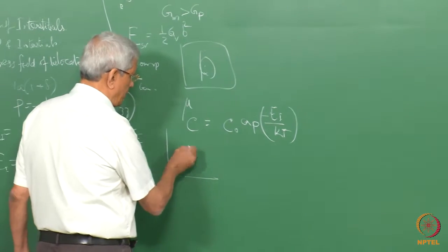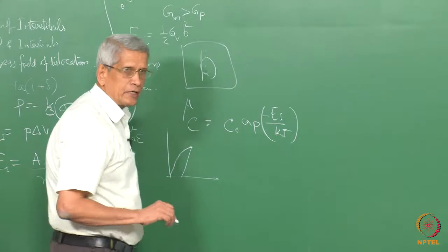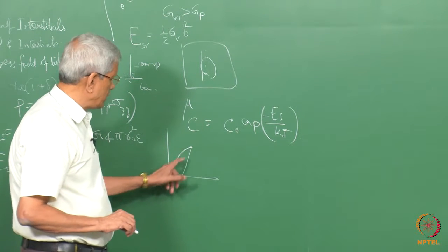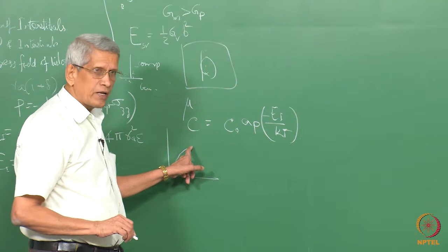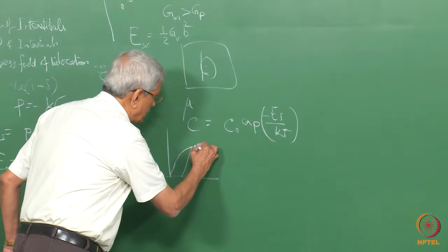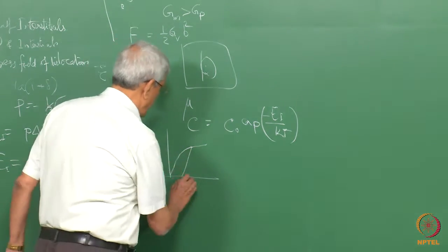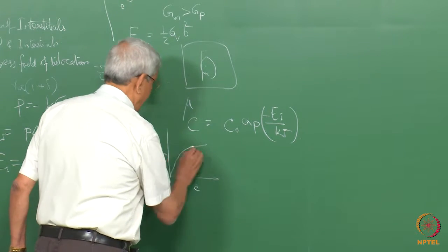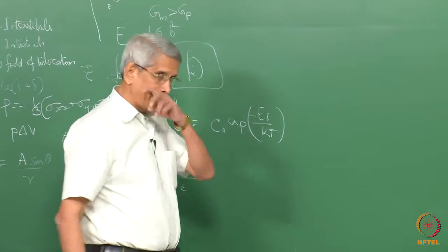It has reached some particular point, I unload it and bring it to room temperature. If I load it again immediately, then what I will observe is that at the same point again the yield stress will come, and the stress response will start from here.